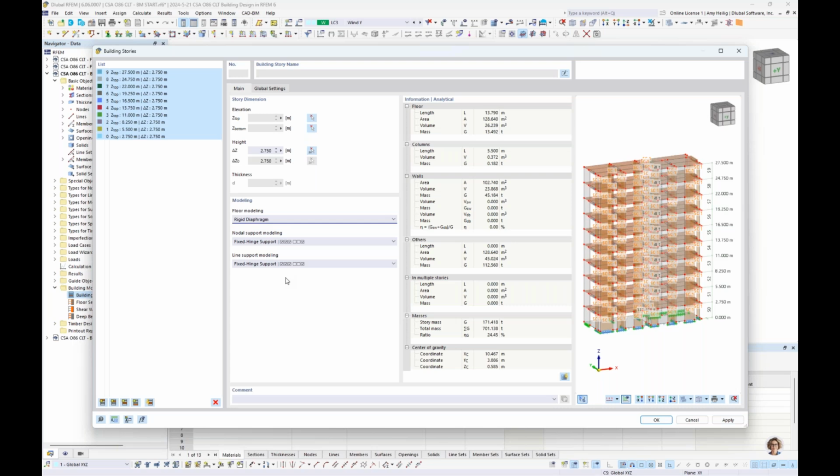So when we extract a single floor element out from the rest of this 3D model, we need to somehow represent the walls and the columns framing up underneath it with support conditions. Again, identical to what we just did in example number 1. The nice thing and powerful thing about the building model is that we certainly can set this to a fully rigid connection for our nodal supports or our line supports, which is more or less what we saw in example 1. But the building model can also calculate the true stiffness of these concrete shear walls or CLT shear walls that are framing up underneath it, or the columns, to apply this as an elastic stiffness instead for both the line supports and the nodal support. So these are the various options that are available to us. Now for our rigid diaphragm today, we're just going to leave this more or less as fully fixed conditions that we see here for the relevant degrees of freedom.